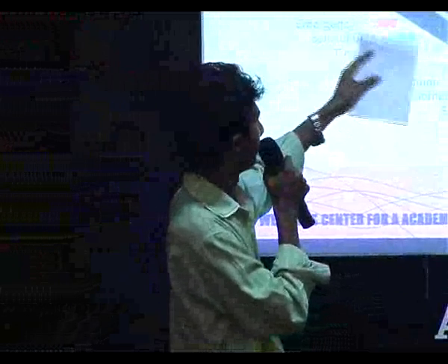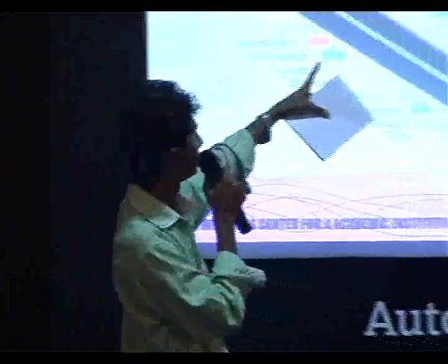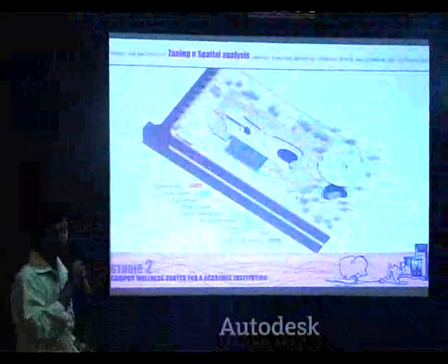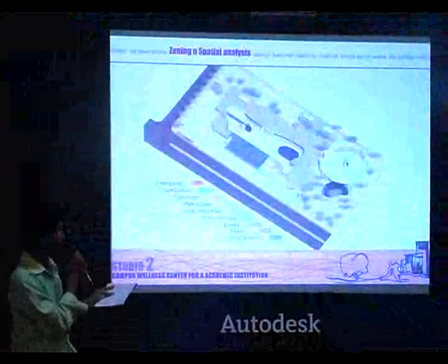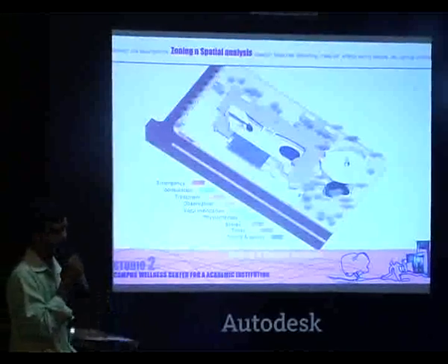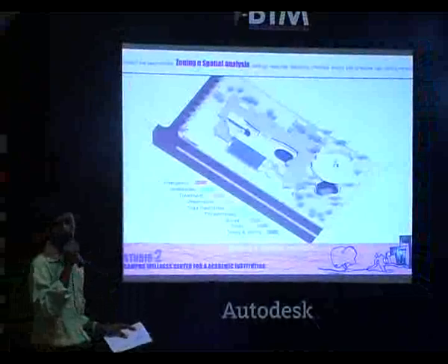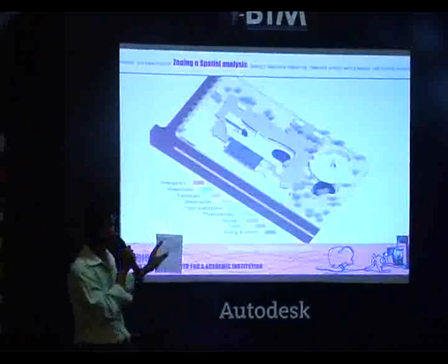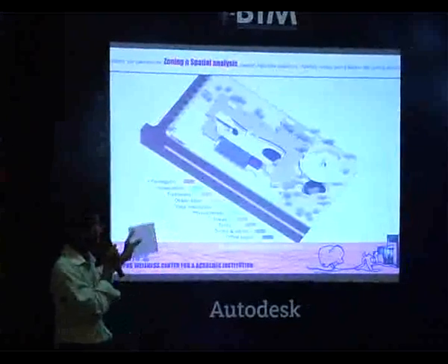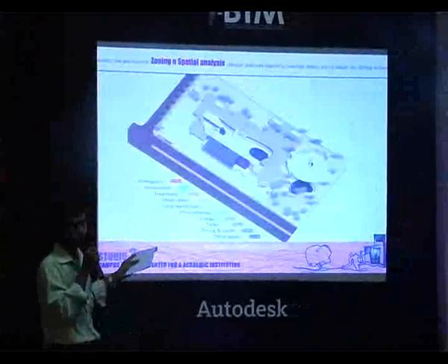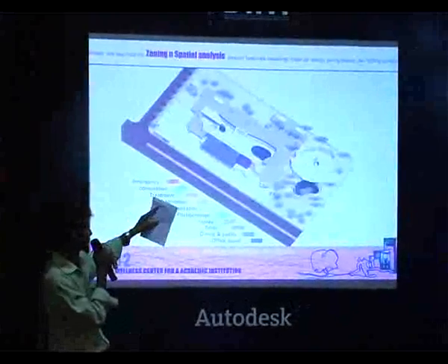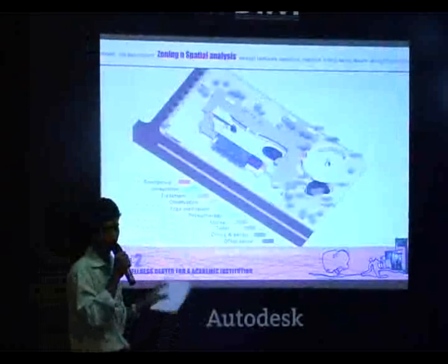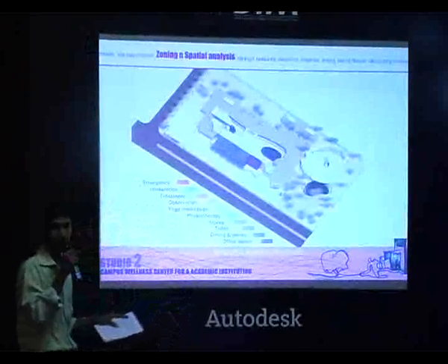Next we have the toilet zone and the laundry spaces. That's the toilet zone, and this next part adjacent to the observation space is the laundry space. We have taken the spaces which are not accessed by the patient to the first floor. All the spaces accessed by the patient are kept on the ground floor. This space is purely dining and pantry. This may not be accessed by patients, but only by persons who are supporting the structure. This particular part is office space. The better thing is that if you stand in the office space, you can have a look at what's happening in the emergency ward.